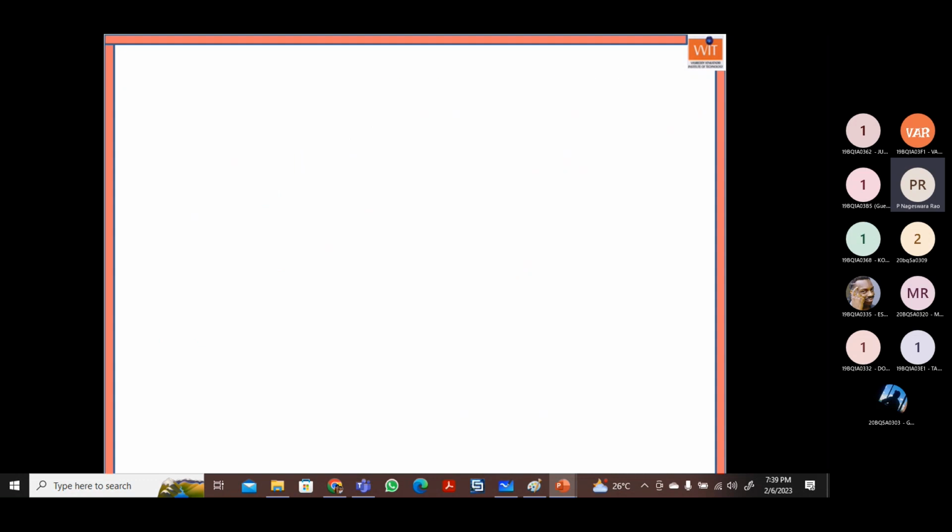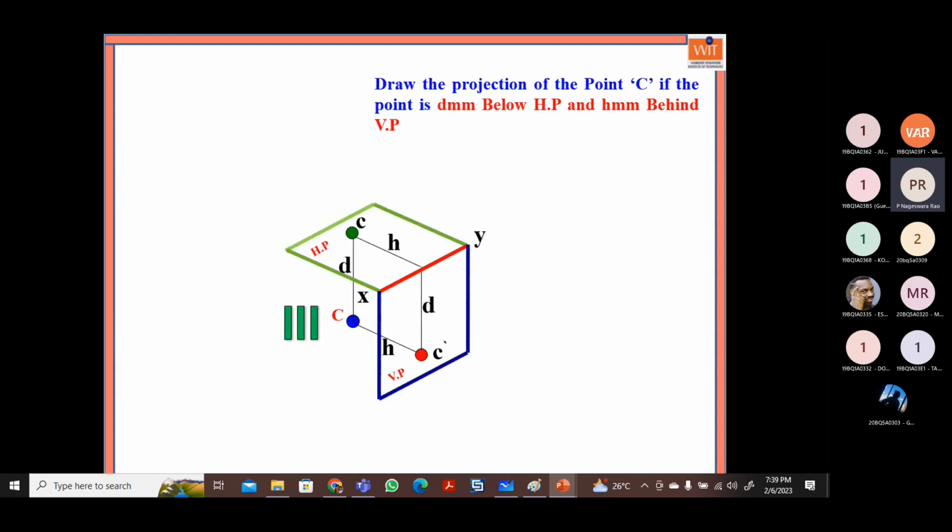Now similarly, when you take the object in the third quadrant. Now the object is in the third quadrant here. So this is the object. Now the observer will always be here. When I send the light rays here, in this direction you will get the image in the front view on this vertical plane, and similarly when you send the light rays here, because this is the transparent plane, we will get the image on the horizontal plane. This is the top image. Because I want to make it a plain paper, as we are going to draw on a drawing sheet, it is a plain paper.